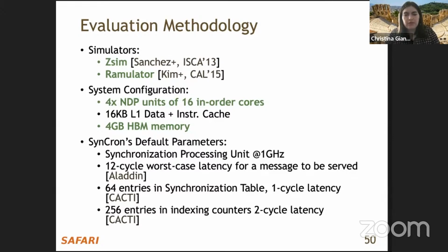And we use a small synchronization table and a small set of index counters which have 1 cycle latency and 2 cycle latency respectively, according to the CACTI tool.